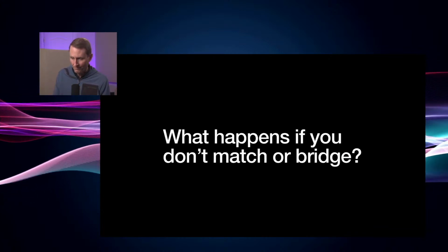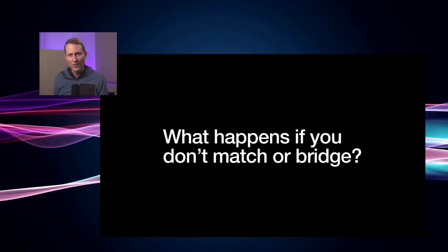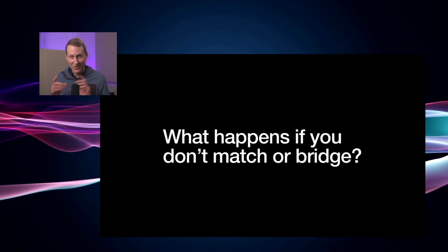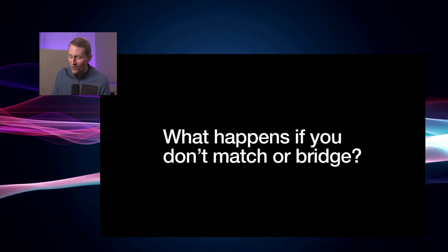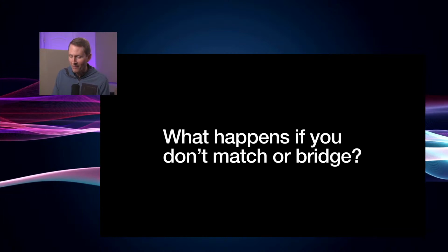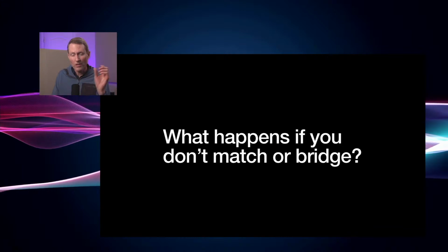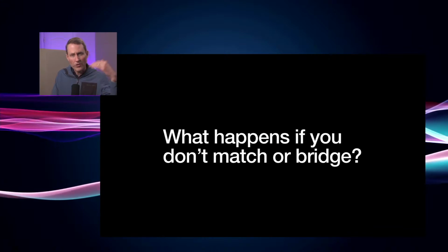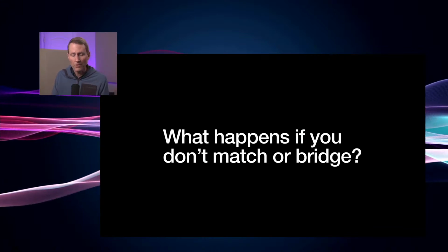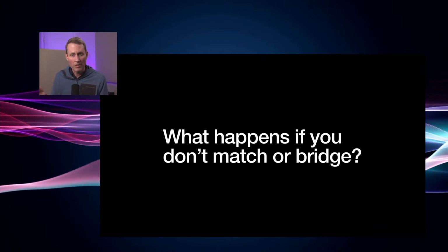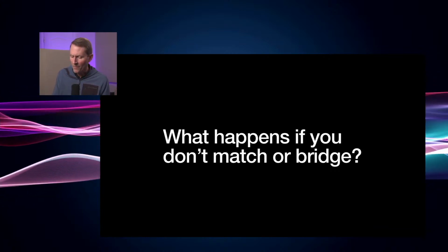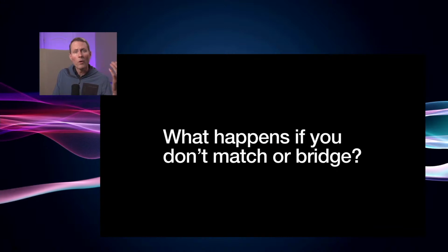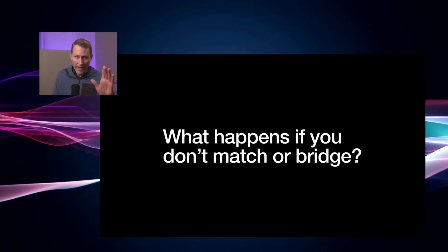So here's the question. What happens if you don't do matched impedance or you don't have a bridging impedance? What happens to your signal? Usually it won't destroy any microphones, but it may not sound optimal. I think it can color the sound a little bit, or it can reduce or change the expected levels of the microphone. So you may need some additional gain or a little bit less gain, depending on the particular microphone and preamplifier that you're working with. And it can color things. So you might get more bass response or less bass response.